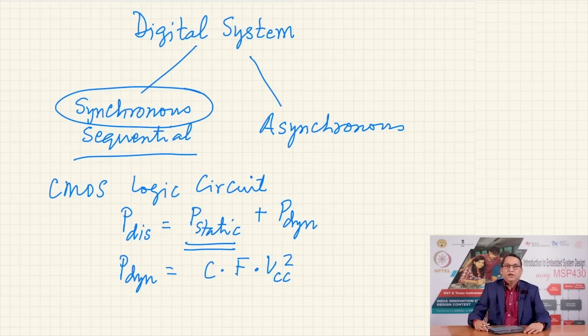So, if you increase the clock frequency, that would consume the battery faster. If you double the clock frequency, it will double the power dissipation, which means it will empty the storage, that is your battery, in half the time. Now, this is one argument why you should keep the clock frequency low.